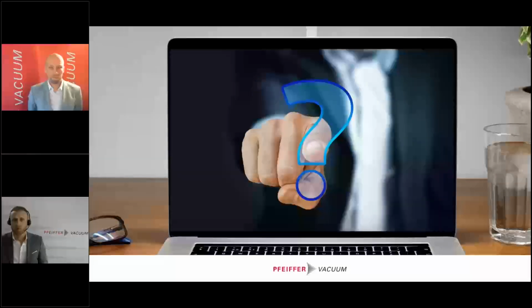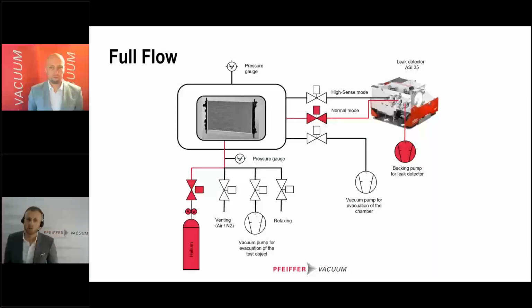Now that we have spoken about the partial flow, we want to show you, of course, the opposite method, which is called the full flow. So in this case, the test object is also evacuated and then pressurized. And then in the next step, you will see that the helium is going 100% through the leak detector. And this has the same advantages that were the disadvantages of the partial flow before. So now you have a much better intensity, but of course, a lower suction speed and therefore a slower response time.